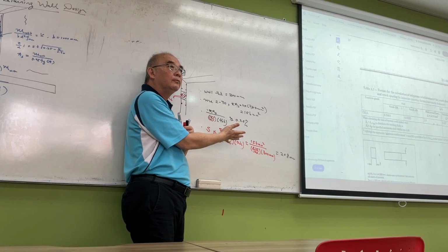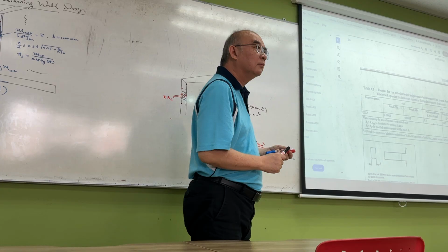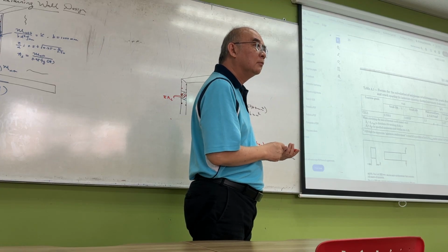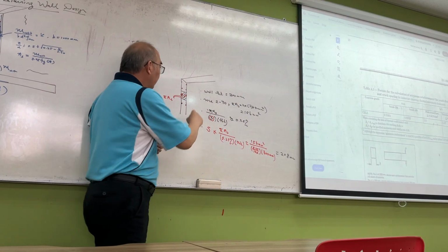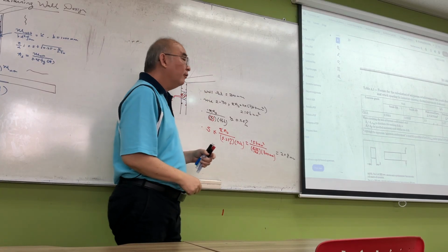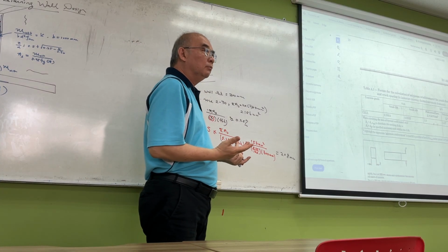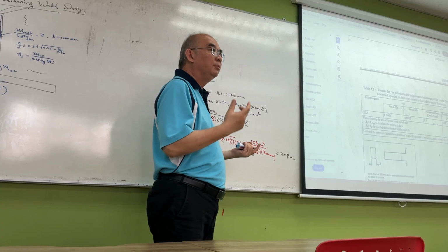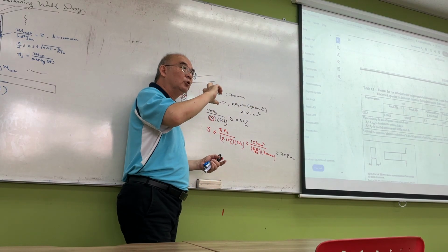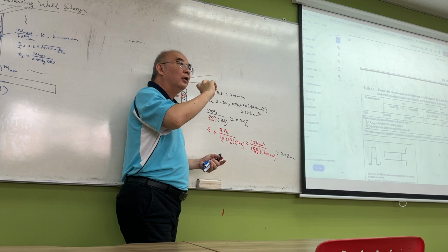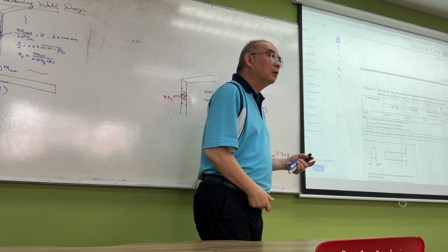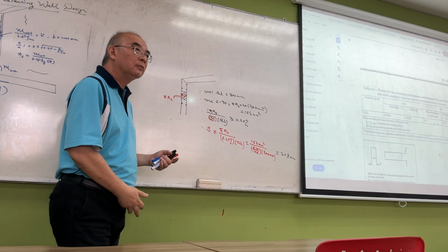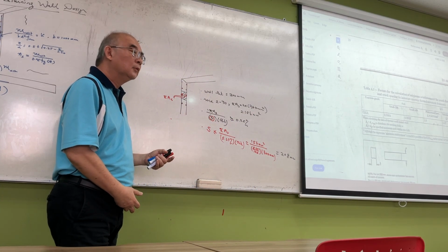Can I use the AS, right? I use the area of concrete. I use 1,000. 1,000 also can. If you use 1,000, then you will have how many bars? Because you do not know how many bars to put in yet. But I know the diameter, the diameter of the bar that I want, so I can find the spacing.